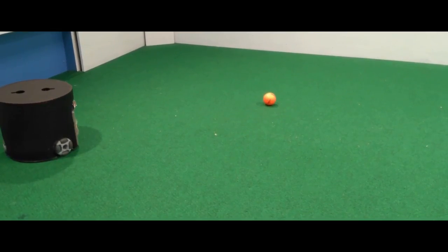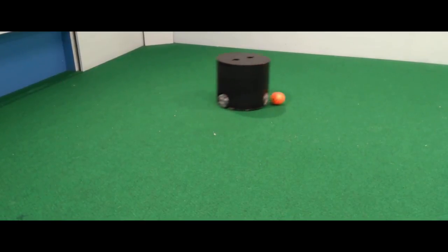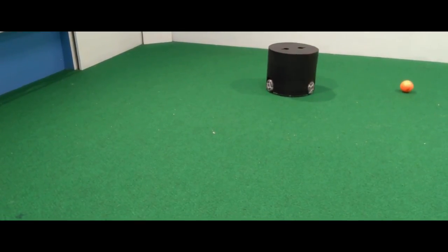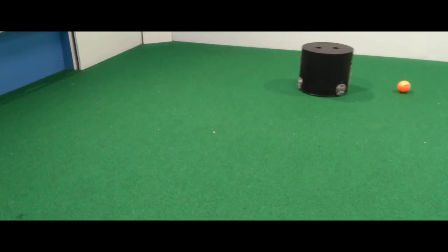The computer vision module's role is to accurately identify objects of interest based on their colour and communicate the object's distance and bearing to the AI navigation module. The module takes raw frames from the Raspberry Pi camera in the RGB colour space. The colour space is normalised to eliminate noise and shadows by dividing each channel's value by the sum of the 3 values combined at each pixel.